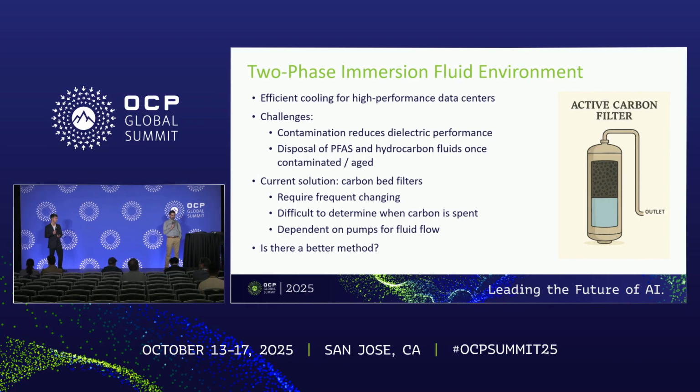But the problem with these filters is that they have a limited lifespan due to a variety of complex factors like contaminant load, the operating conditions, and the potential for moisture ingress. And this is a dynamic process, so it's kind of hard to identify or establish systematic maintenance. So regular monitoring is required to avoid overload in your filter.